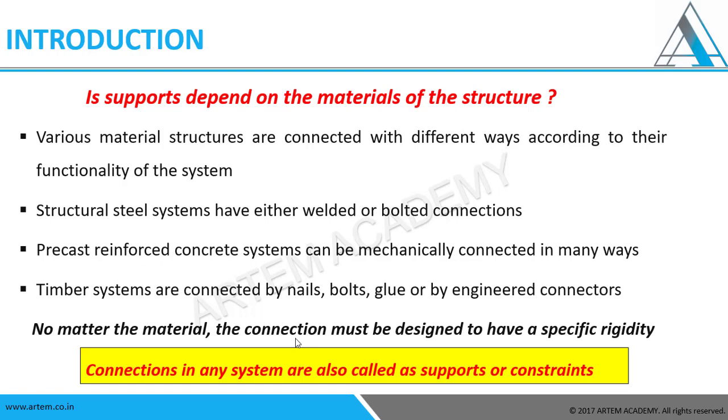Most of us will have a question: do supports depend on the materials of a structure? Let us throw some light on it. Various material structures are connected in different ways according to the functionality of the system. Structural steel systems have either welded or bolted connections. Precast reinforced concrete systems can be mechanically connected in many ways. So while carrying, placing, and in functionality, we will have different supports. Timber systems are connected by nails, bolts, glue, or engineered connections.